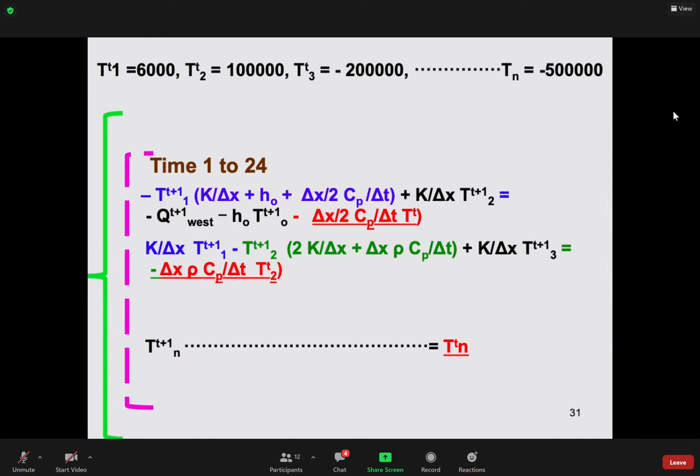And in most problems we do not have the value. If I want to design a building, I do not know the temperature of the wall, because the building has been there for some time. What I do is guess some value and solve it with this technique. Then I can run this program for the whole winter and look at the temperature variation on the wall. Whatever the initial value was disappears.